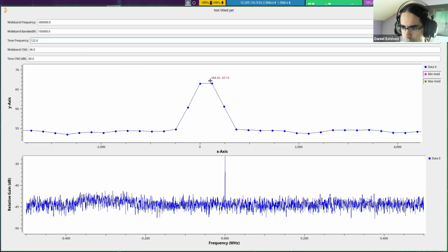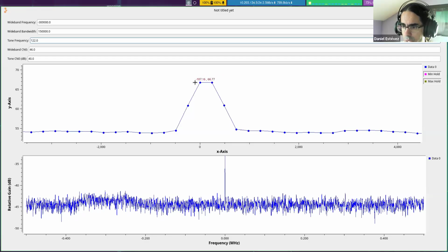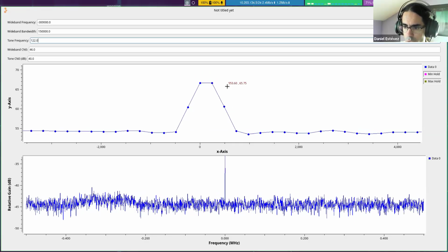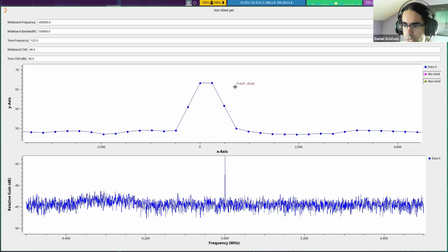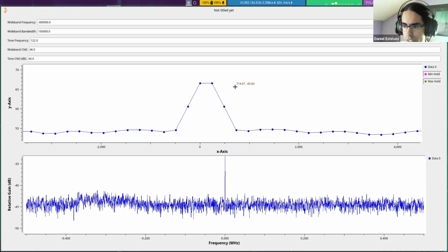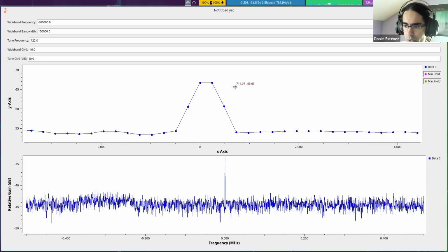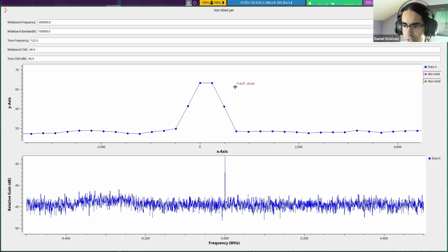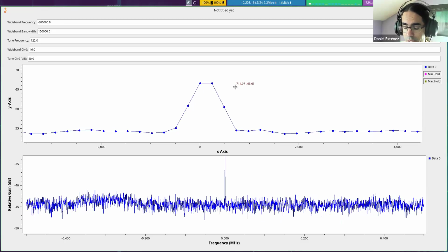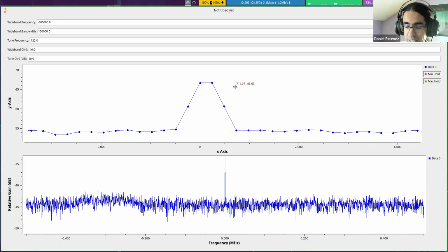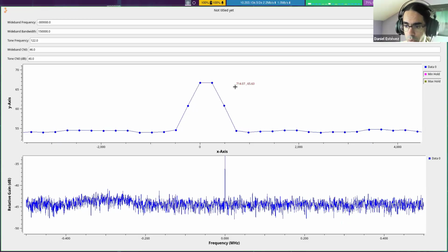But if now the signal is halfway between the bins, it needs to be distributed between these two. So this effect is called scalloping losses. If you hear about scalloping losses, that is the thing we are talking about. And the thing which determines how large the scalloping losses are, and also something else which is called spectral leakage, is the FFT window.